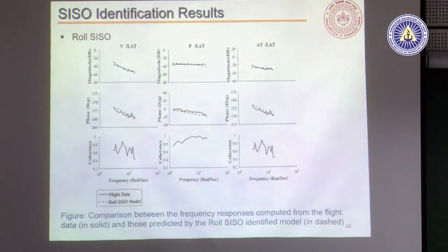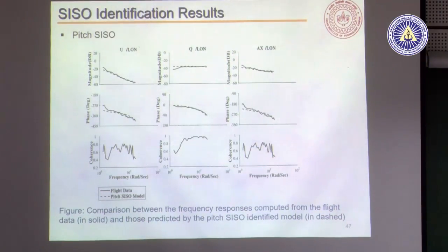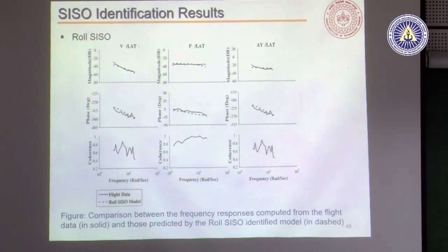This is the pitch, this is the roll, again a similar thing. Compared to this, roll has slightly better low frequency correlation, because in roll I can give smaller inputs and my motion is relatively smaller. Roll motion is relatively slower also because the drag is higher. In pitch your velocity is typically faster for the same input, because your frontal area is smaller. In side flying your projected area is higher, so it will have more drag. So you can relatively give low frequency inputs somewhat more easily. Here you can see slightly better correlation at the lower frequencies.